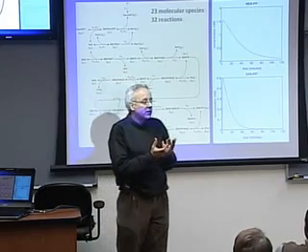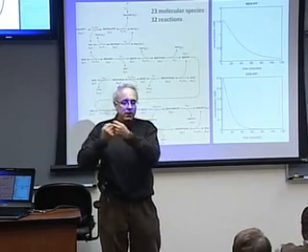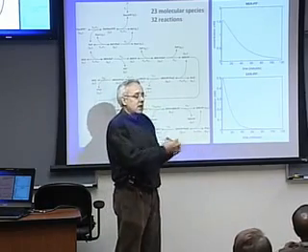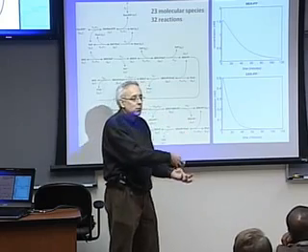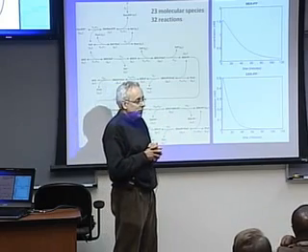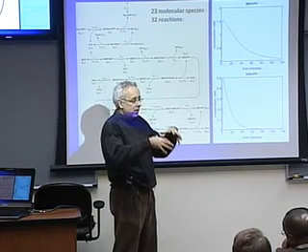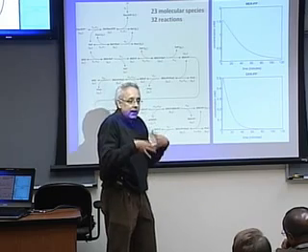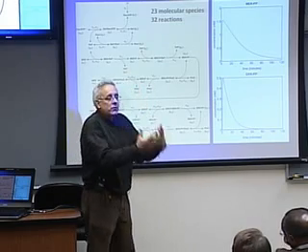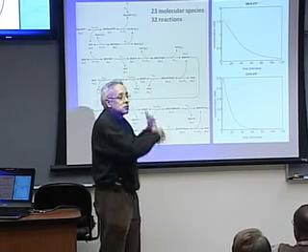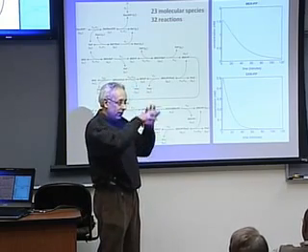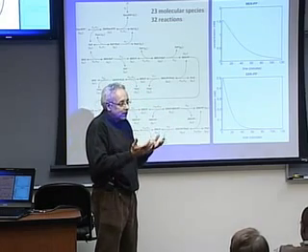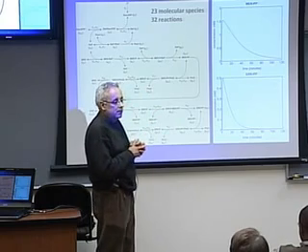So if I find rate constants where small changes produce large changes in the output, and I find some other parameters where large changes don't produce any meaningful changes in the output, then the second set of parameters will give me the idea that the reactions associated with these parameters are not very important. So the system is robust to those reactions. But in the first group, the reactions associated with these parameters are very crucial. This is what sensitivity analysis tries to do in this framework.